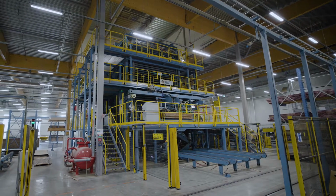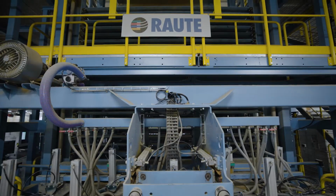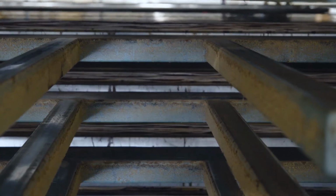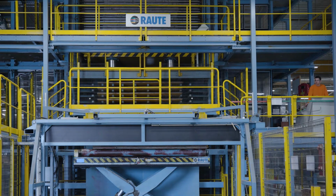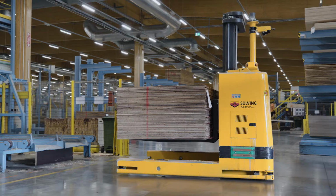Hot pressing brings each plywood panel to its final mechanical strength. Plywood panels are first pre-pressed at room temperature to make them strong enough for automatic handling. Then, the panels are compressed between hot press platens to finish curing the glue between each veneer sheet.